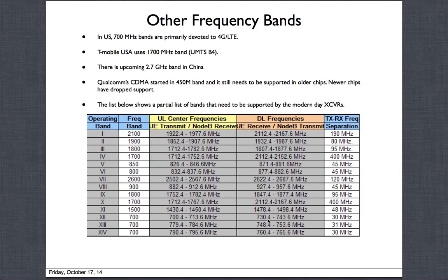For example, you take this 30 to 43 megahertz, which is about 13 megahertz. If you have 13 megahertz bandwidth, LTE supports many bandwidth modes up to 20 megahertz. You cannot support 20 megahertz here. It is also going to be hard to support 10 megahertz, because you're giving that whole 10 megahertz to a single carrier, a single service provider. So this does not even support 10.